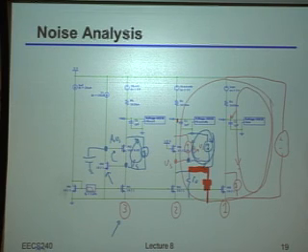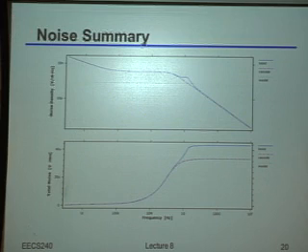So this picture is showing a simulation, basically repeating everything I just said. I apologize for the labels not being so great. There's a green line that you probably can't even see, so let's not compare it. The pink line versus the blue: pink is number 2, just the cascode, and blue is the gain-boosted cascode. This plot shows the noise density versus frequency, in other words, the power spectral density of the noise.